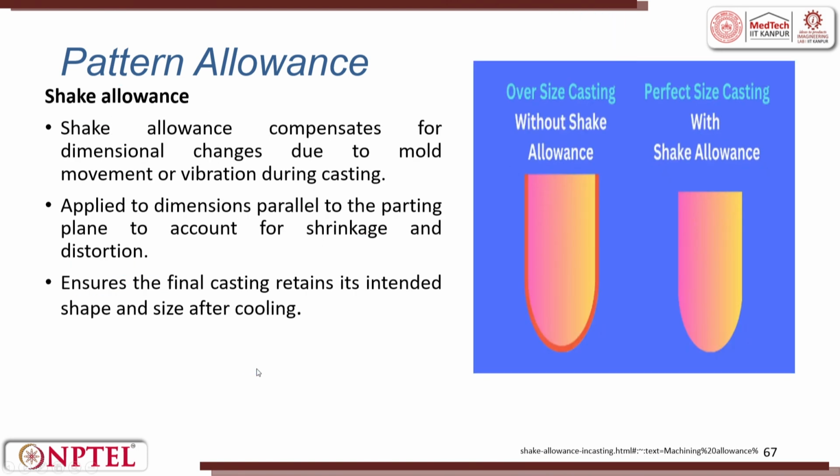Shake allowance: draft allowance is for removing the pattern, while shake allowance is generally given because we shake and then take the part out. The shake allowance compensates for the dimensional change due to the mold movement or vibration during removal. See, when you try to remove, we shake and then remove, right. It is applied to dimensions parallel to the parting plane. The parting plane is where you have the cope and the drag; this is the parting plane.